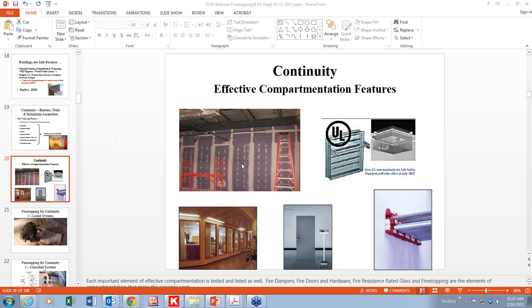Cracks in drywall that are continuous likely might breach the fire resistance rated assembly. Why? Because the fire test was run on a solid piece of gypsum material, anchored a certain way, with the joints taped all together as one piece. It wasn't tested with holes in it. It also wasn't tested with cracks in it. Maybe one of the manufacturers, U.S. Gypsum, National Gypsum, Georgia Pacific, has tested these assemblies with cracks in them. Really where you need to go is the manufacturer of the wall to see what crack is allowed.